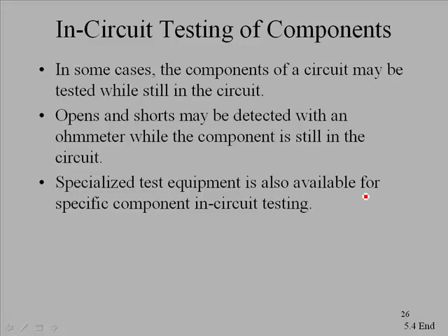components in circuits. This is often a tricky thing, though, because when you measure across a specific component, oftentimes that component is in parallel with other components, and so the reading that you would expect with it out of the circuit and when it's in circuit is often very different. So you have to really know what you're doing in order to do this effectively.